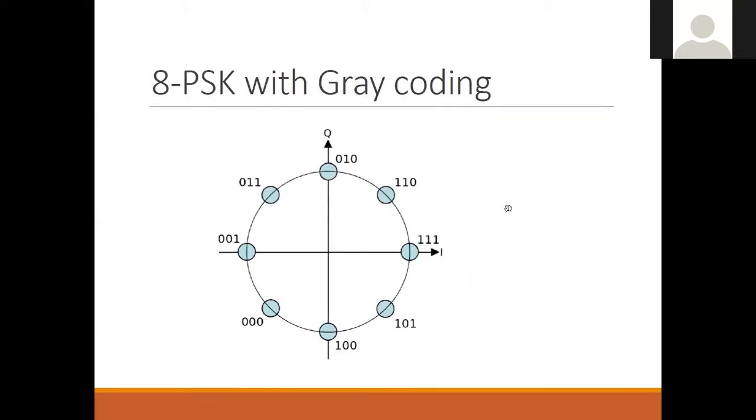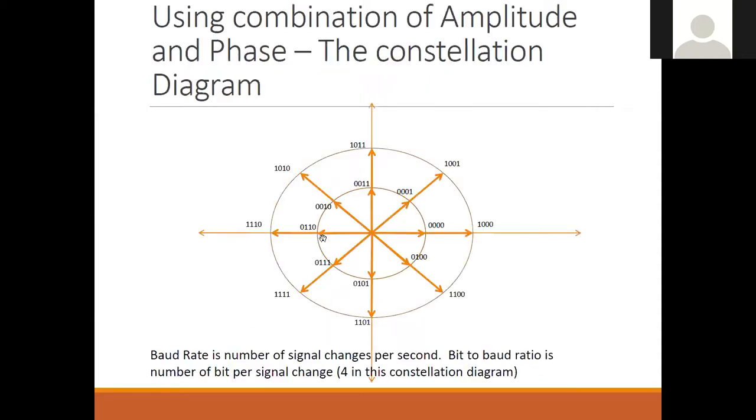If the errors are okay, then depending on the signal strength, it will shift to this one. If that is fine, then it will shift to this one and go up to a 64 or 128 point constellation diagram, or 256 point constellation. On a 256 point constellation diagram, you get the maximum speed connection with your Wi-Fi.